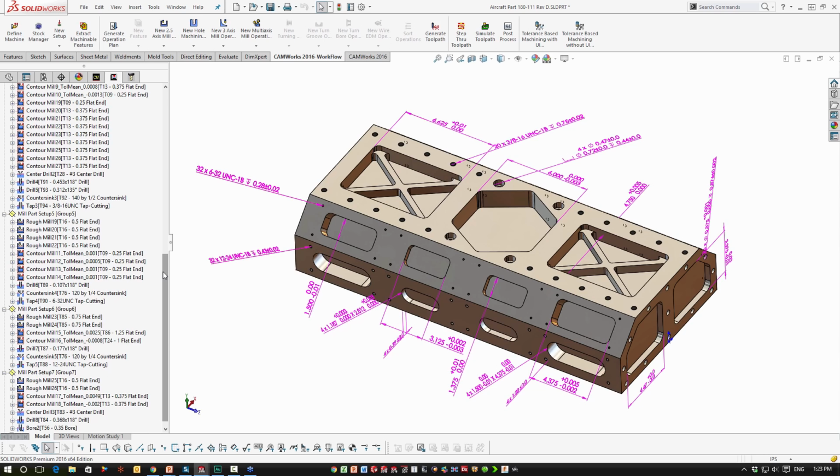It's going to make creating the drawing itself much simpler, and it's going to mean that the 3D CAD model that gets passed to the machinist contains all the information, and nothing's going to be left up to the interpretation of the drawing. I think we've probably all seen drawings that are so crowded, very difficult to interpret, and possibly contain too much data. It's over-constrained. By putting these tolerances in the 3D model, it eliminates a lot of that.